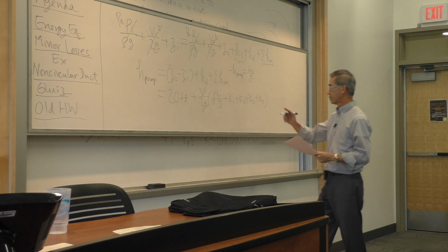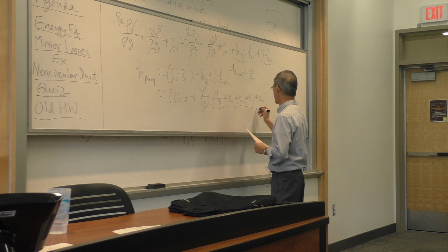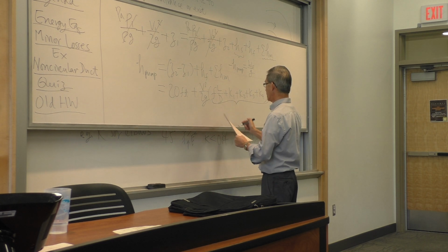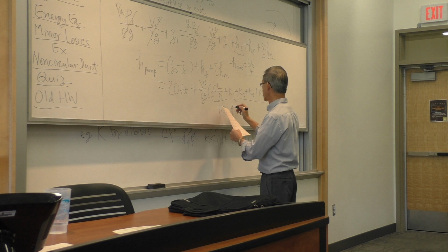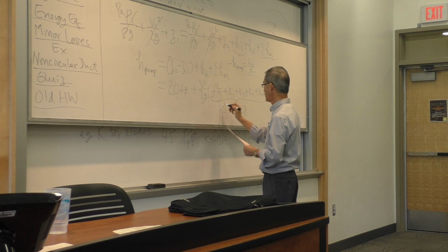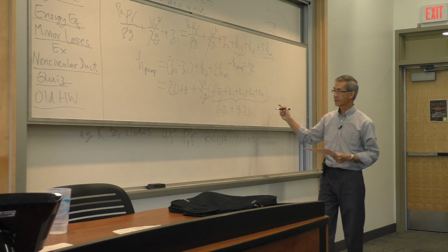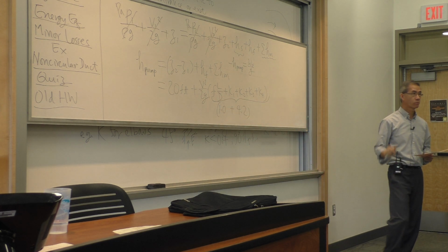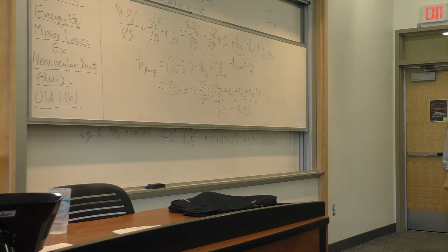And if I use all the values on my far left, my Moody diagram losses is equivalent to about 1 within this parenthesis, but the so-called minor loss is so deceiving. It's 4 times that of the frictional losses due to shear.